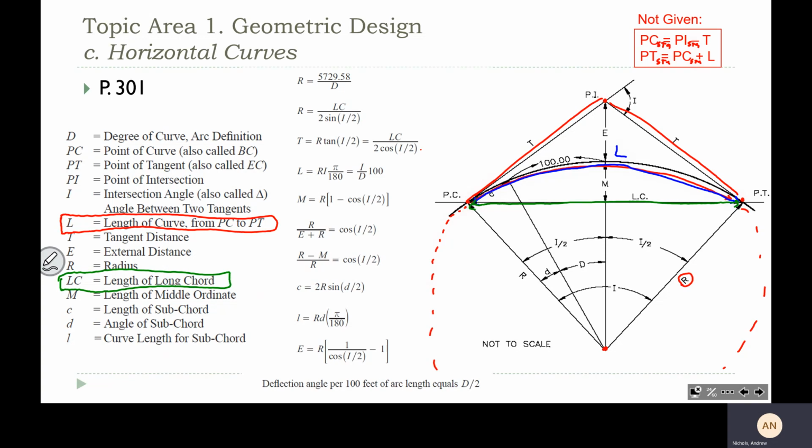And this is possibly one of the most confusing concepts, even when you go through intro to transportation, as well as geomatics, since this is covered in geomatics as well. So whenever you're initially laying out a roadway, this tangent section is extending all the way down here, and then you get to the point where the road needs to turn. This tangent all the way up to the PI, and this tangent is already defined. And so the surveyors can lay out stationing along these tangents, and so you'll have a PI station that has been calculated. So let's say that's 10,000.